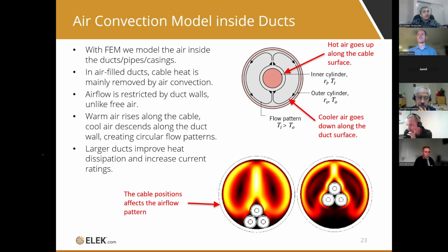The IEC specifies that the range is about 25 millimeters to 100 millimeters for the duct size. So duct size is limited between those dimensions, which is very limiting and not really applicable to HDD, right? Yes, and another major assumption is the position of the cable in the center of the duct, which is always assumed. If it's an air-filled duct, it's impossible to have that.